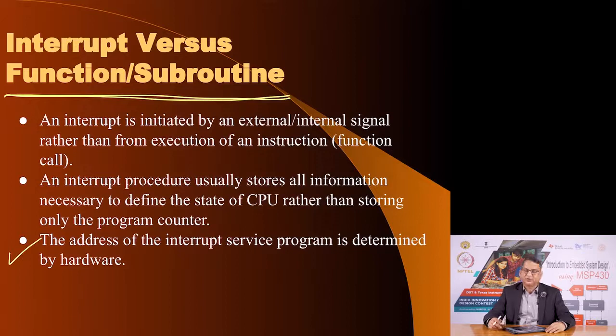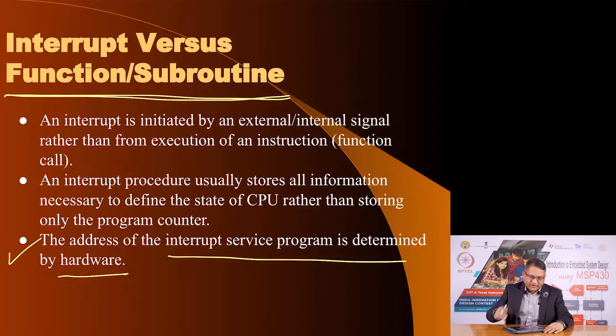The address of the interrupt subroutine is determined by the hardware. The address of a normal subroutine is determined by the software. Depending upon how big your code is, the assembler or compiler will put that subroutine at some place, and that place can change, but the subroutine for an interrupt is decided by the microcontroller, meaning by the hardware, and when we see the details you will realize what I mean.